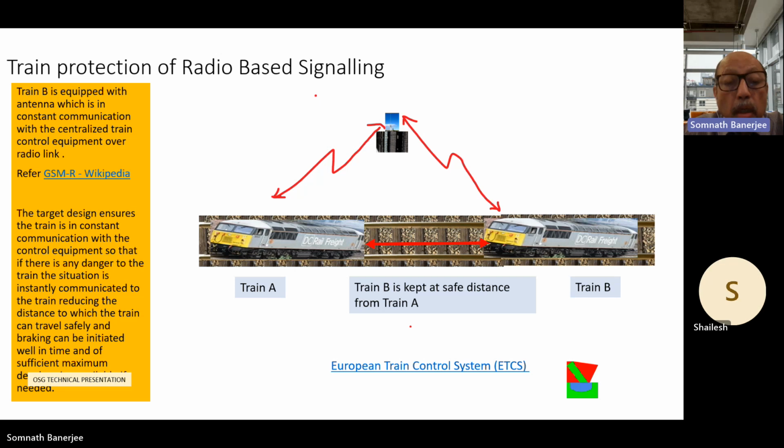So when the safe distance to which a train in rear can be allowed to go is computed, the train will be provided with a distance-to-go information from which the error of localization of the train in advance is subtracted. So it will never happen that train B will actually collide with train A, because the errors are always handled in this fail-safe manner.